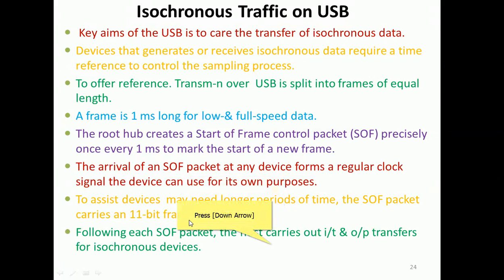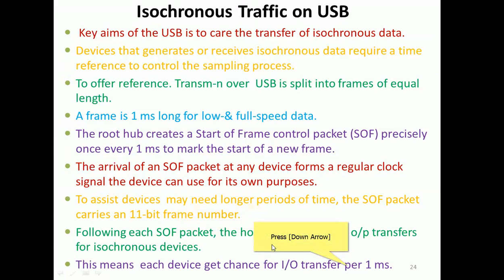Following the SOF packet, the host carries out input and output transfer for isochronous devices. This means that each device gets a chance to transfer every 1 millisecond.